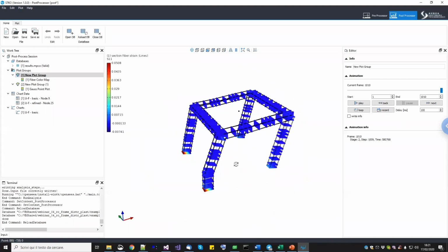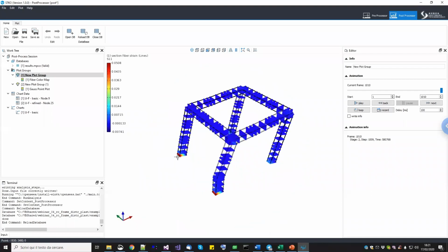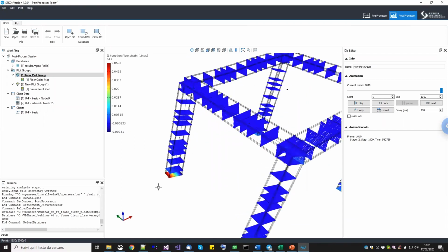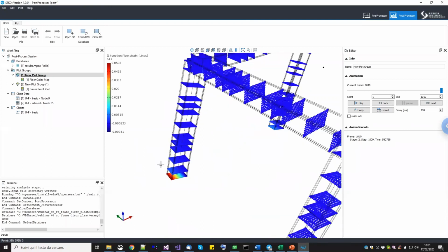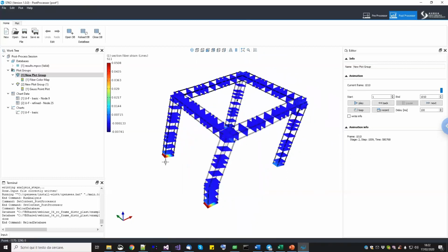Well, this is another problem related to strain localization. Before, there was a nice localization of bending. Why? Because in this kind of model, the curvature was linear. So a linear curvature means that the finite element method already knows which Gauss point should localize, because it's the one that during the entire analysis has the larger curvature. Unfortunately, the shear strain is constant over the element. So each Gauss point has the same shear deformation, but then it also has the same shear stress. So which Gauss point should localize?